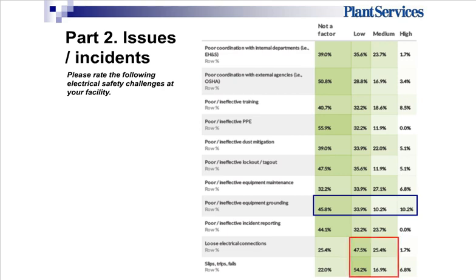And I do want to point out that if you look more towards the middle, people who reported the most problems, not necessarily high problems, but low to medium, were having issues with loose electrical connections, splits, trips, and faults. Now, I know Corey's going to have some thoughts on this because he has seen the whole data set. Some questions that we asked, we are reporting, such as how many of you use portable IR cameras, and also how many of you use IR windows on panels. This question especially seems to point to the fact that those who are using those tools are finding these kinds of problems, that IR cameras most quickly pick up those sort of loose connections and grounding issues.